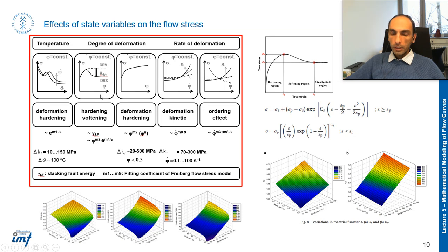You know that you may have the recovery. Okay, if you do not have the recovery and the dynamic recrystallization, then the curve would be like this. So the flow stress increases, I can say, all the time till it becomes plateau at the end. But when you have the recovery, then it drops a little bit, and if you have the dynamic recrystallization, it shows such a behavior here.